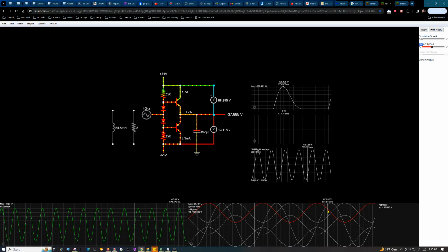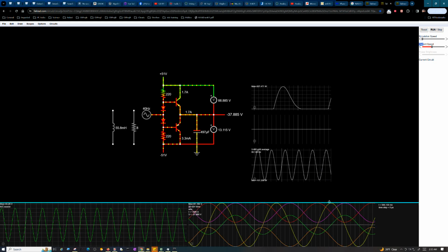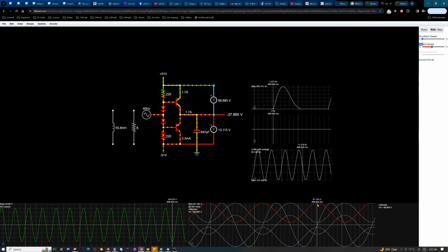But the one thing he doesn't talk about is the fact that our peak voltage is actually 91 volts. And that's not just 50 volts plus 10 volts or something. That is because this transistor at some point is operating too, and it pulls this voltage, it stretches it down below ground. So in effect, as this transistor is doing its thing, the voltage is actually much, much higher, but that's not where peak power occurs, because basically the transistor is kind of off at that point.